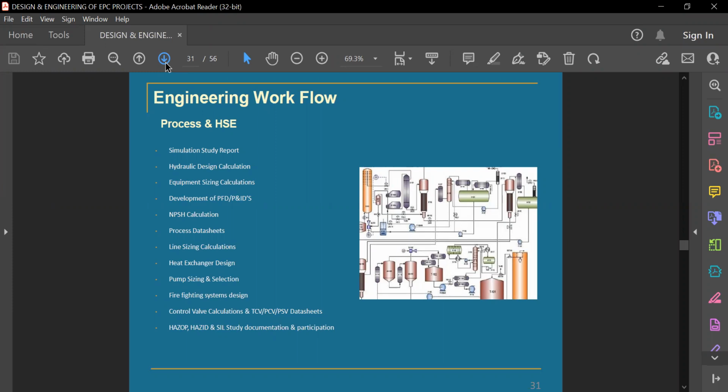And then for example, if I have put in three transmitters and one transmitter fails, another will take over, and then the third one is also there. But if the valve on which I am taking action fails, if it is stuck, if it is not closed when the demand comes, then I will be in trouble, and then I will have to have one more valve.